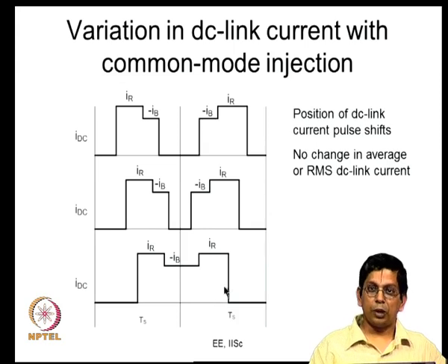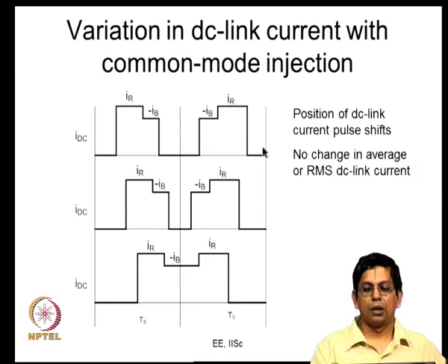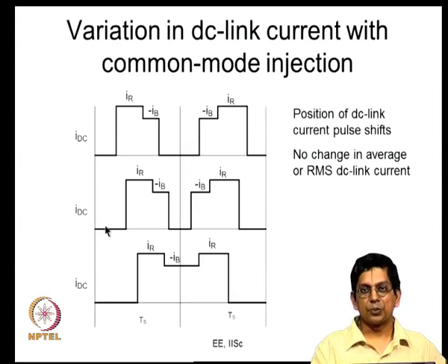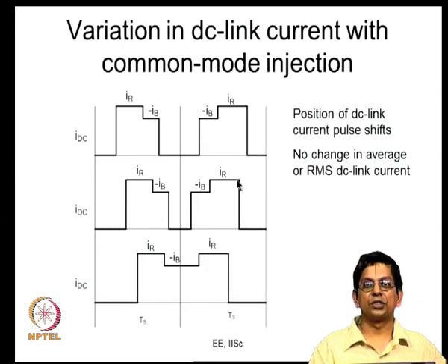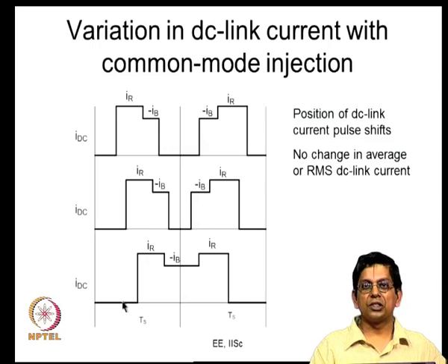So, in continuous PWM schemes such as conventional space vector PWM, if you look at the DC link current, you can actually say what the switching frequency is from that. So, this region from 0 to, because it is going through 0, this is one half of a switching cycle, one subcycle. So, this is actually one complete switching cycle, alright. Now, this happens like this, so it goes around. So, what is the difference? The pulse position actually shifts, but does the average value of IDC over the subcycle change?